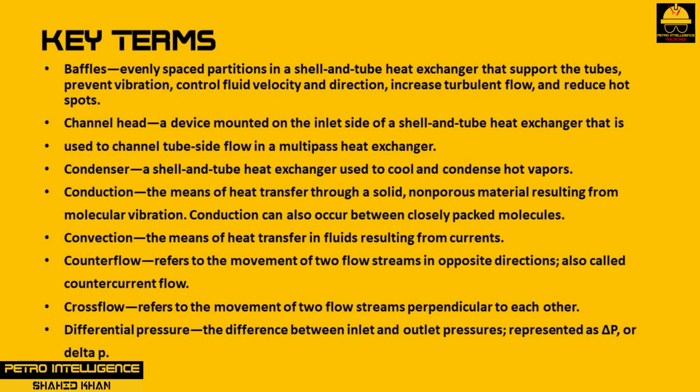Baffles are evenly spaced partitions in a shell and tube heat exchanger that support the tubes, prevent vibration, control fluid velocity and direction, increase turbulent flow, and reduce hotspots. Channel head is a device mounted on the inlet side of a shell and tube heat exchanger that is used to channel tube side flow in a multi-pass heat exchanger. Condenser is a shell and tube heat exchanger used to cool and condense hot vapors.